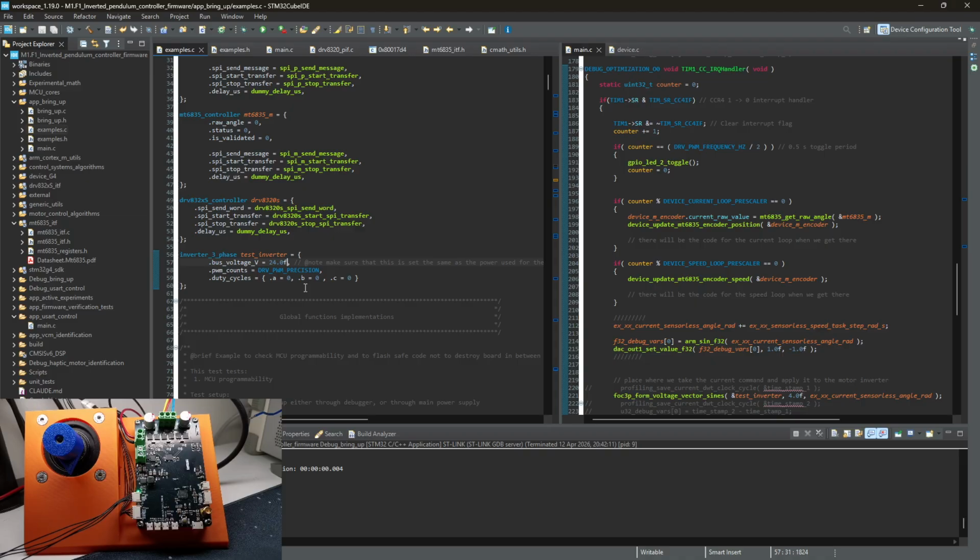If that FPU uses more cycles and slows, if I understand. No, FPU is actually a very cool thing. FPU is the same as ALU, but for the floats. The problem we face right now is that FPU, like on STM32, only works with float, with floating point values that are 32-bit wide. And double is a 64-bit wide floating point value. And FPU cannot handle this. So it has to do operations outside of FPU.